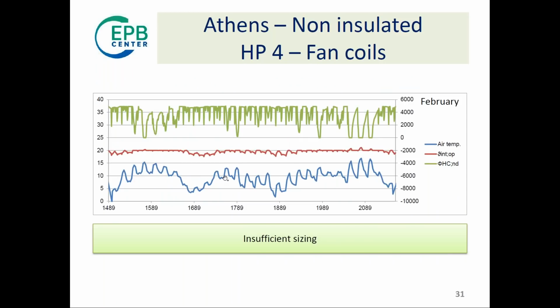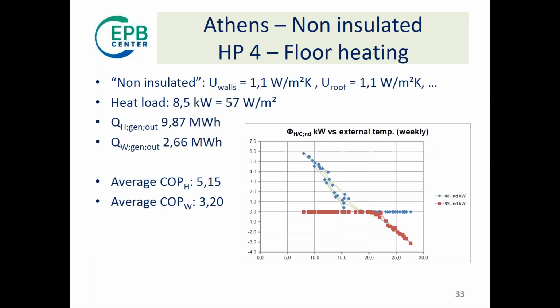And if we have a look, the smallest heat pump is not really enough. You see here in February, we have some days where the heat pump cannot match the load. The smallest peaks here repeatedly are the storage reload, but this curve is the fact that we are not matching the required load for heating. So we should shift to the heat pump, probably the Model 6, and to fulfill our heating. But nevertheless, it doesn't change the results about the COP. This is just a question of identifying a discomfort.